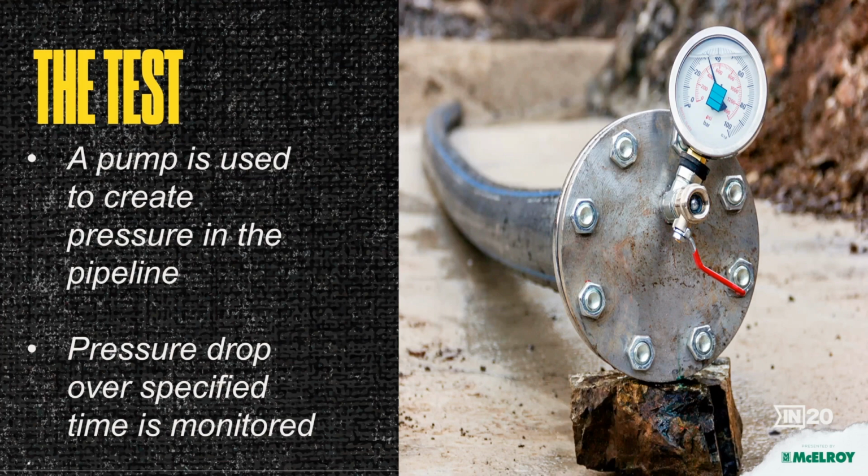Now, there are some intricacies to the test that differ depending on the type of test, procedure, or material being used. For example, some tests require cycling of the pressure in the line to simulate expected surge or other things of that nature. But at its core, it is pressure it up, monitor it for leaks, hold the line under pressure over a period of time.